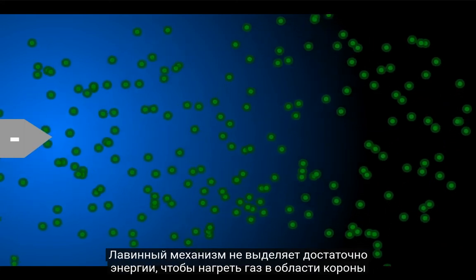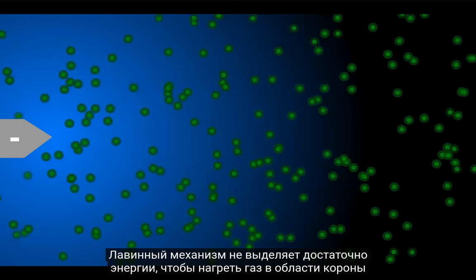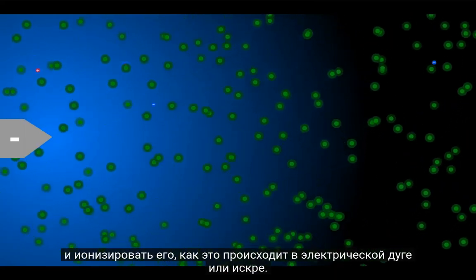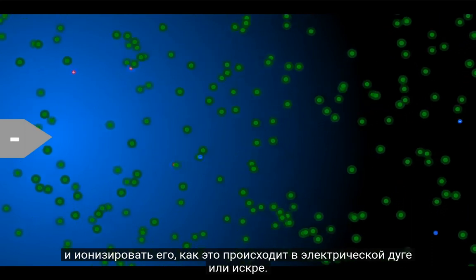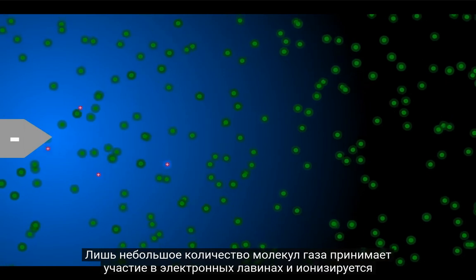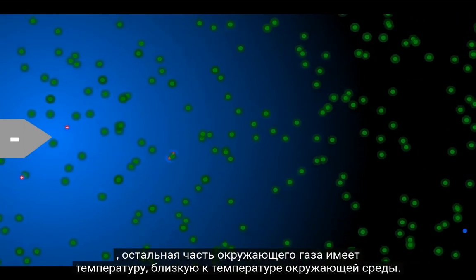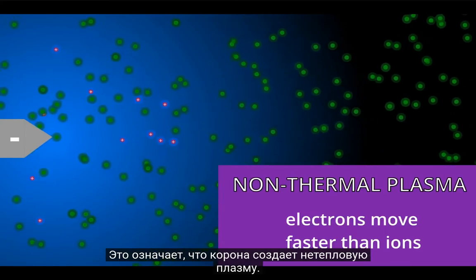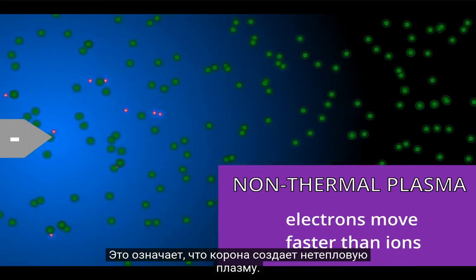The avalanche mechanism does not release enough energy to heat the gas in the corona region to ionize it, as occurs in an electric arc or spark. Only a small number of gas molecules take part in the electron avalanches and are ionized. The rest of the surrounding gas is close to ambient temperature. This means that a corona creates a non-thermal plasma.